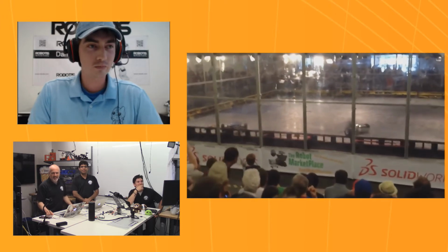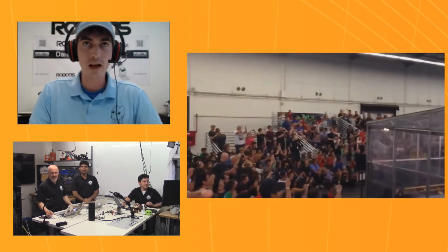Wow, that's awesome. What are these blades made of? A lot of aerospace engineering materials, like titanium, but usually the weapon tips are made out of an alloy called S7 tool steel. That particular bar that Last Rites is running is a 2024 aircraft aluminum bar, and it has steel tips. The moment arm on that when it spins up is just tremendous, because the further you can get your dense mass away from the center of rotation for the same angular velocity, you get a ginormous increase in the amount of stored energy.